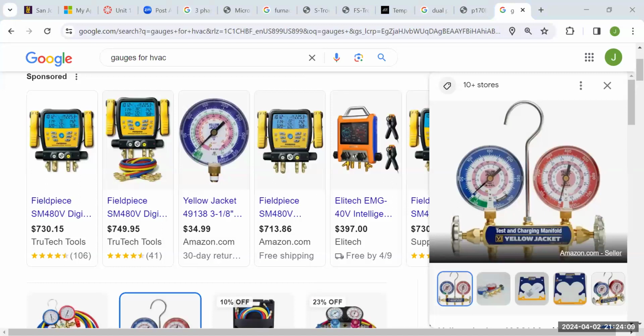All right, the thermocouple consists of two dissimilar metals joined end to end, has a hot junction and a cold junction. The two metals are not brass and steel. The two metals are iron and Constantan on the thermocouple. When these metals are connected, they form an electrical circuit, and current will flow when heat is applied to one end of the device. So when we apply heat to the hot junction, we're going to get a small amount of current flow through those dissimilar metals.